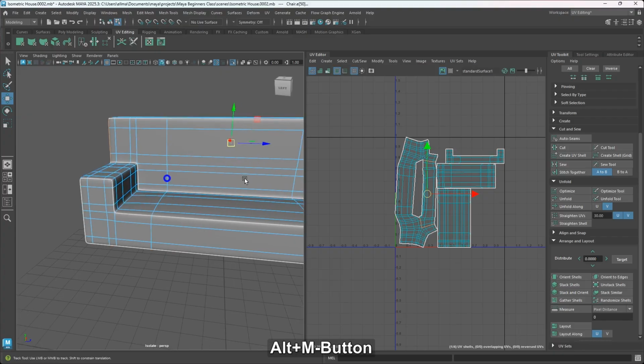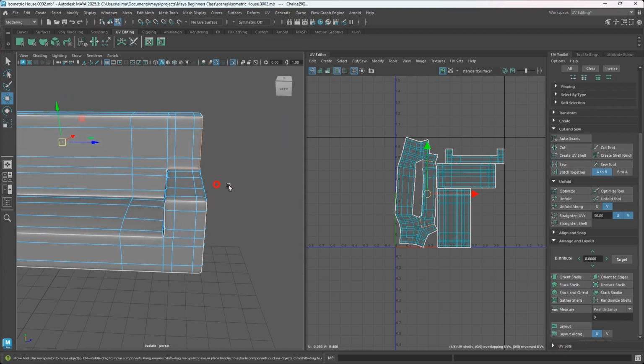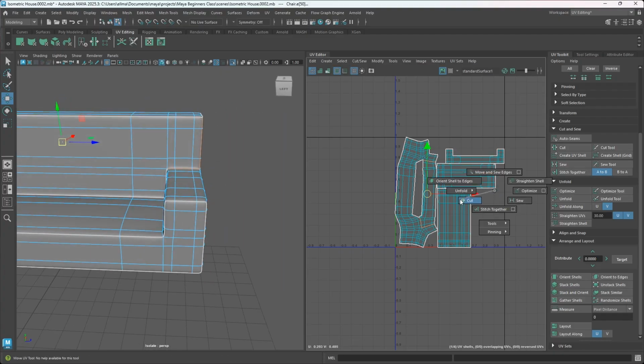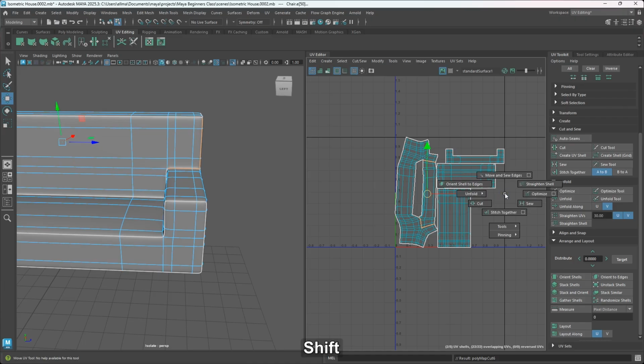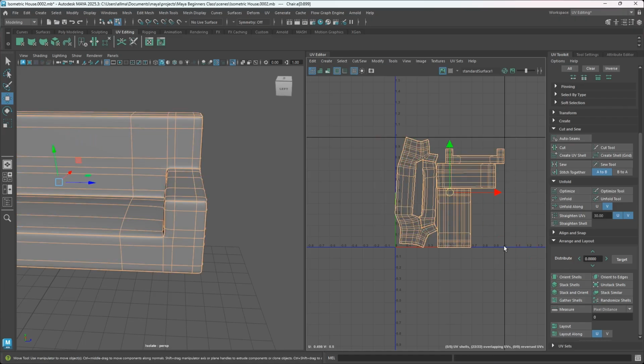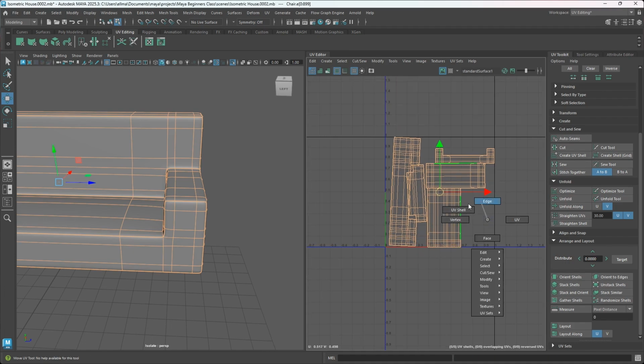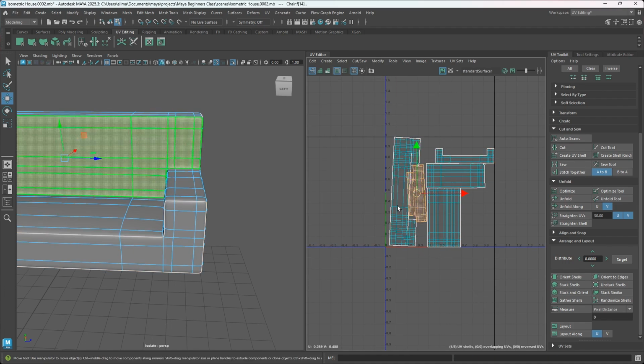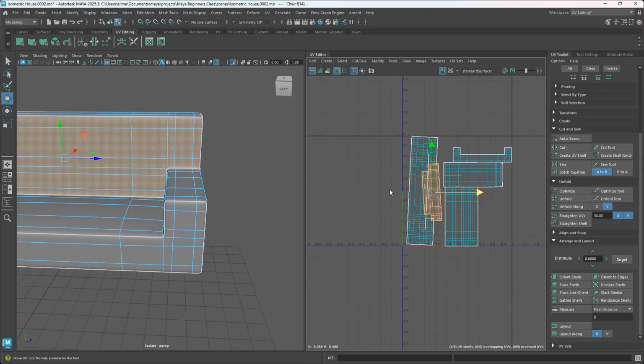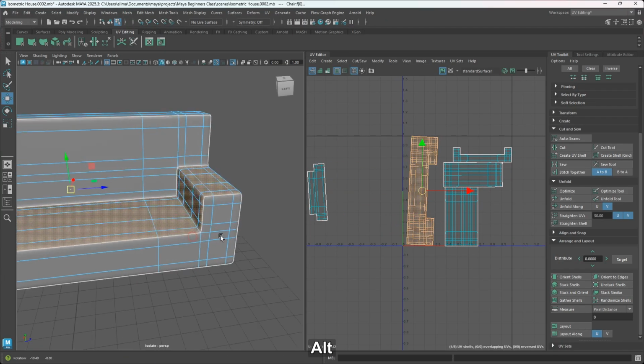Yeah, we're going to add a loop there. Now right click, shift right click, cut, and then highlight all, hit on unfold. Then let's right click, go into UV shell. Let's select this shell and let's see. So let's bring this here. Let's select this one.